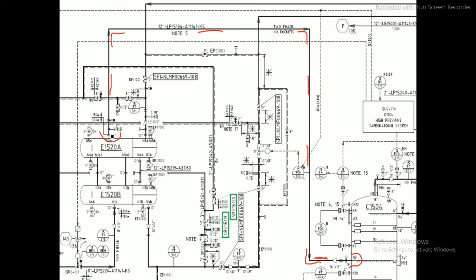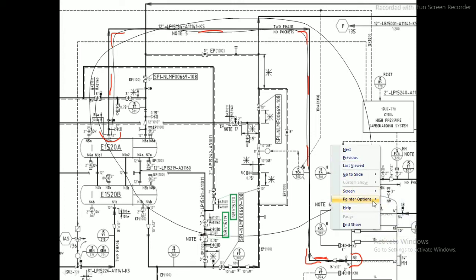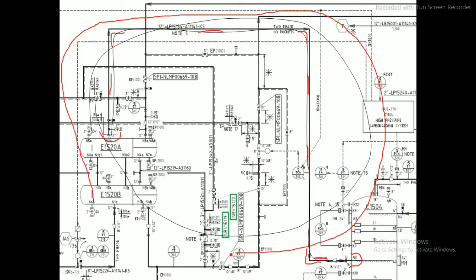Again you have got a line, and the line from the equipment is going outside. So what is required? He places one drain over here, we have a spectacle line, and then the line goes here and connects to the equipment. So you have to understand just one line. You don't have to see a whole P&ID at a time, because it is not possible to read and understand the whole P&ID at once. You have to take one line, and see how it travels and connects to another equipment, because it will be very easy to understand things that way.